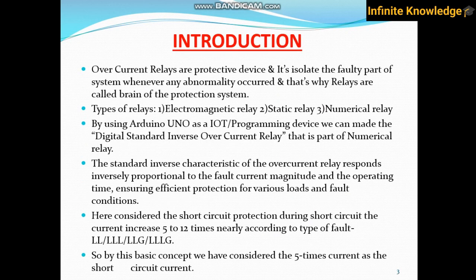And this is the introduction part. So what is the basic introduction? Overcurrent relays are protective devices. Why is it a protective device? Because it protects your electrical system, your electrical appliances, your whole electrical grid from any faults, like line to line fault, line to ground fault. Here all the things are mentioned. So whenever any abnormality occurs, it isolates the faulty part of the system.